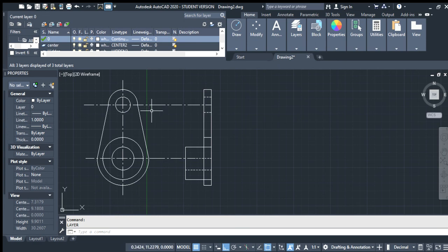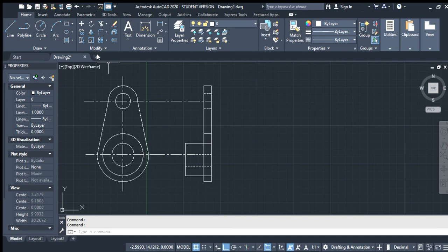The last thing we have to do is do dimensions. So we'll go ahead and close the layer window. This video is running a little bit long, so if you know how to do dimensions, you can go ahead and end it here, but I'm still going to go over it. We'll go to linear first, and we're going to select the ones that need to be diagrammed. So here, it's going to make me do them each separately. Distance between these two is 3.5. The distance on here is 0.5. The distance on the bottom,